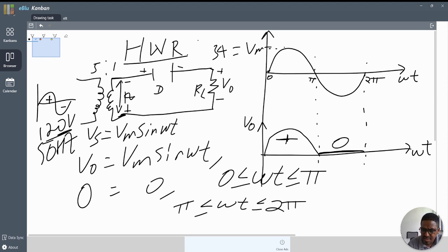So that is the reverse condition of our diode. D1 becomes reverse condition. During forward, from 0 up to pi, the diode conducts, that is the forward condition time. So in one full cycle, we get one pulse from 0 up to pi. That is, we get V maximum.